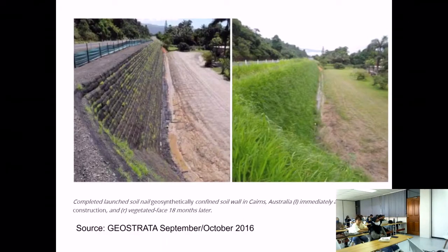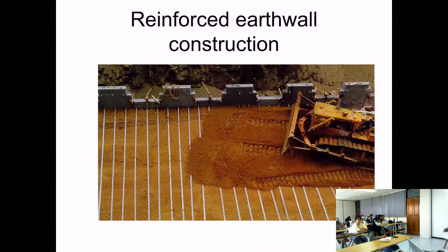So in this case, it's a combination of what we call soil nail geosynthetic wall. When it says soil nail, that means inside this wall, there's a nail that goes into the ground. A nail is usually made of steel bar that is pushed into the ground. And this nail also will be connected to this geosynthetic. Right? Strip material, you saw that just now, that we place inside the soil mass. In this case, a retaining wall.